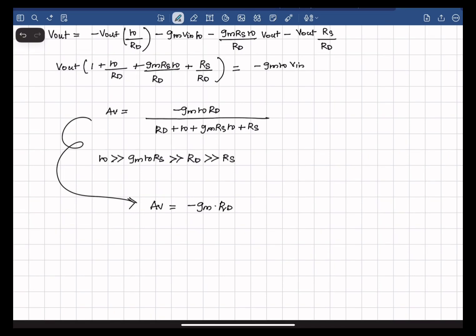A common source amplifier with source degeneration adds a resistor at the source that creates a local negative feedback. This makes the gain more stable and predictable across process and temperature, and it also improves the linearity and reduces distortion. But the trade-off here is it has a lower voltage gain, some headroom issues, and a noise penalty compared to a simple common source stage.